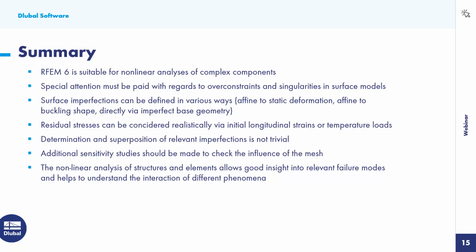But I also want to highlight, and this is my personal opinion, that doing such a type of analysis from time to time, maybe if time allows it in a certain project, you get a much better feeling of the behavior of your elements and your structure if you also activate these nonlinearities and push your model over the linear boundaries, and see the failure modes and spend a bit of time analyzing the results.